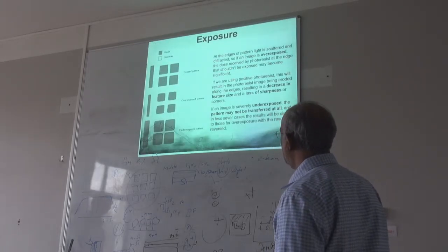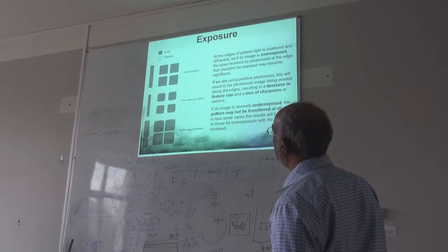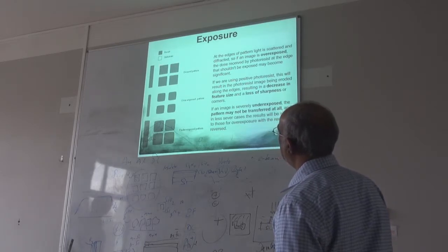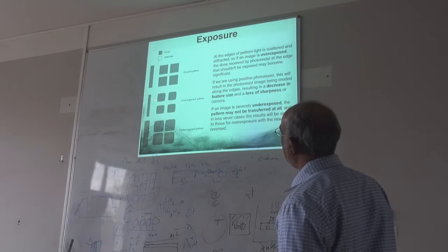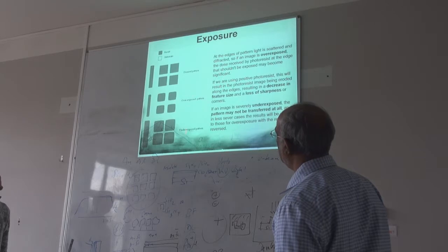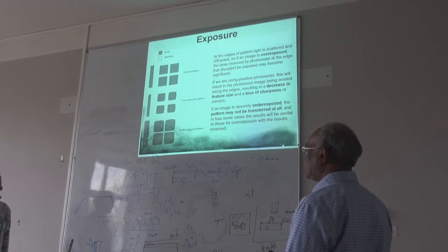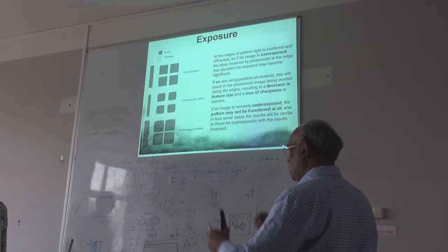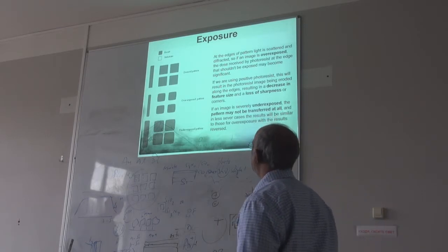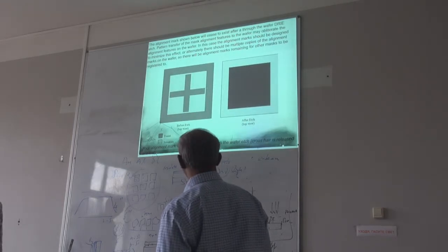But also with the exposure you have to be very careful. This is what you need to have, very sharp edges. If you are doing like this or this, they are not good. This can be due to overexposure, this can be due to underexposure. You should aim for very sharp features. That depends on how long and what dose you are using for the exposure.